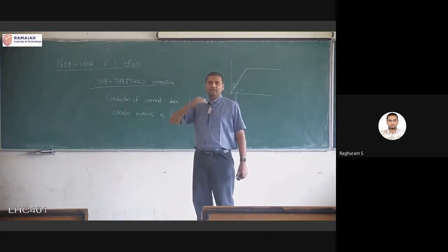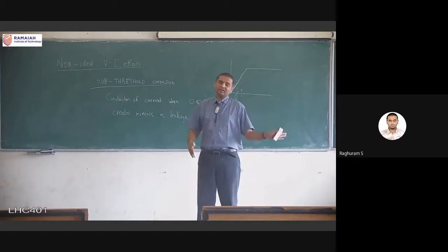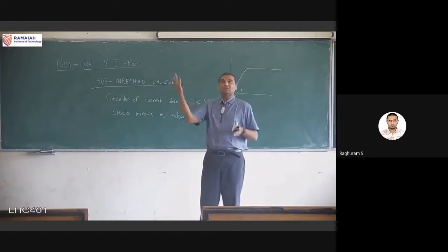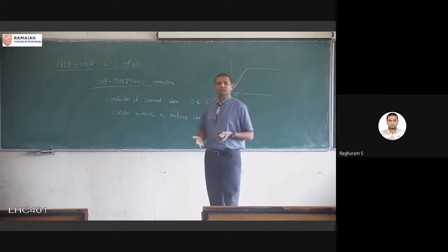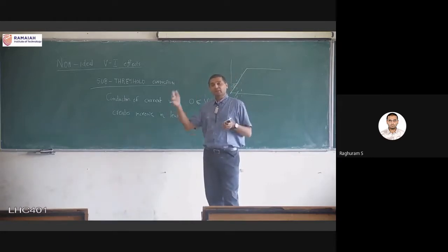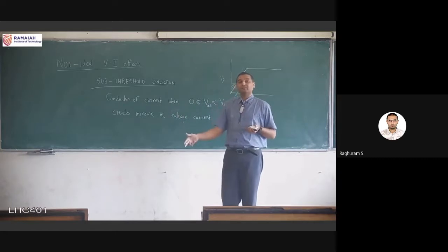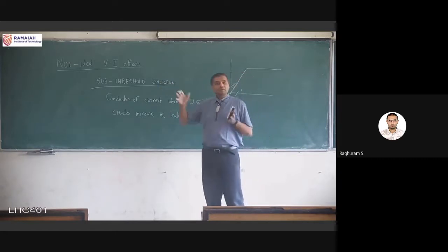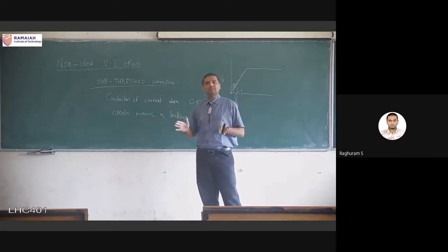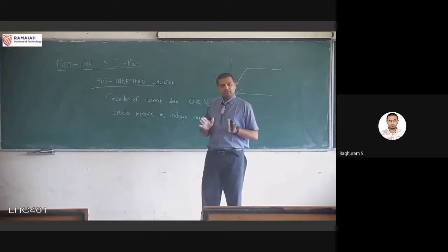Ideally we need current and we always say that we want more current to increase the performance, right? Opposite of that is, if you have less current, performance is lesser. But just like we described this home automation type device, we don't need high performance. There, more important is battery life. So if the whole design is in sub-threshold operation, the performance is lower, great, that's not a problem.